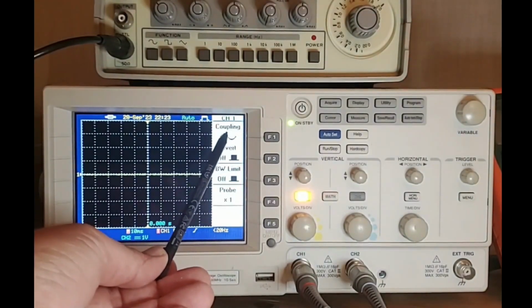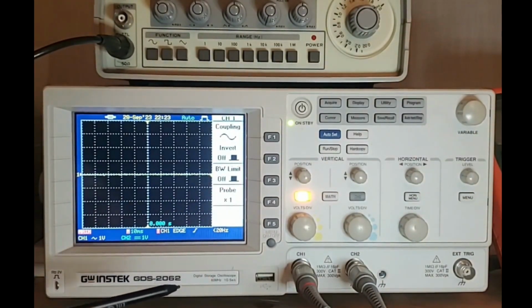However, when we use AC coupling, then the DC component is removed from the waveform that is displayed. So for example, if I have a voltage waveform where I have a sine wave, let's say, of 1 volt peak to peak, but that sine wave is offset at, let's say, 10 volts DC. So this means the maximum is 11 volts and the minimum is 9 volts. So I have a sine wave which is riding on top of a DC voltage.